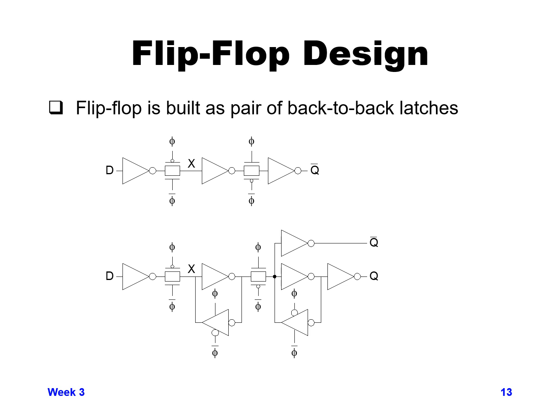And the bottom design you could view as inverter, pass gate, inverter, followed by a pass gate, inverter, and then have an additional inverter if you need a latch or a flop that has both Q and Q bar output. So the top one is a D input and an inverting Q bar output, and the bottom one is a D input with Q and Q bar on the output.